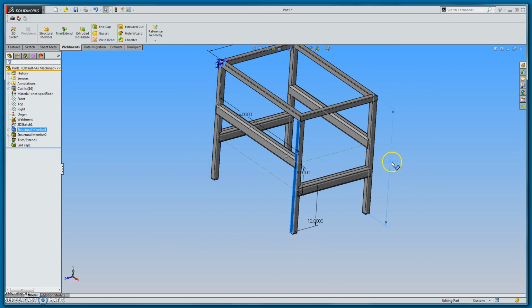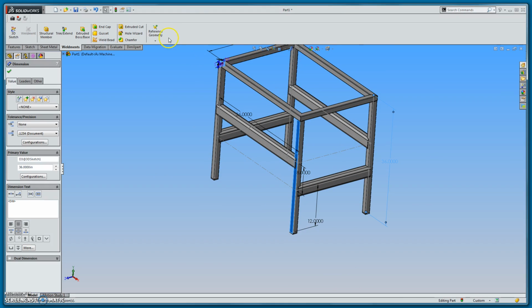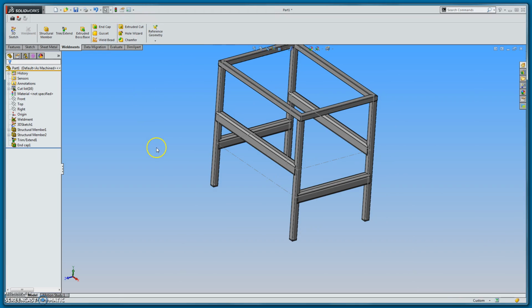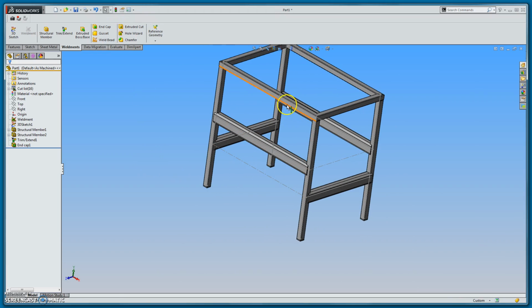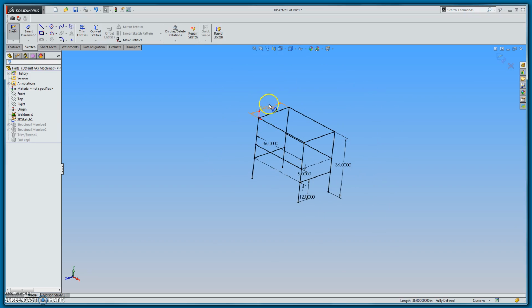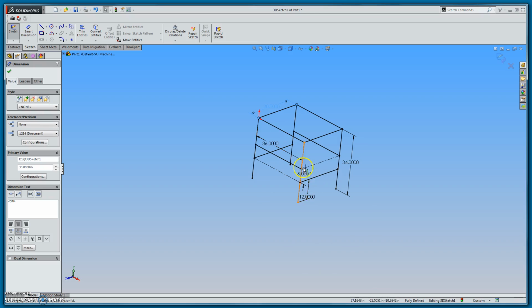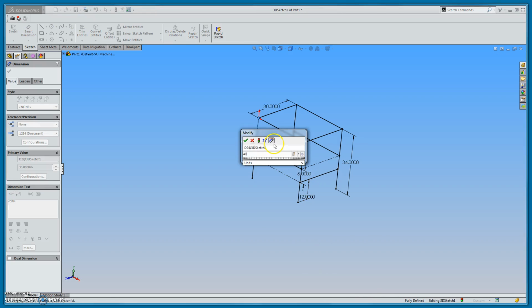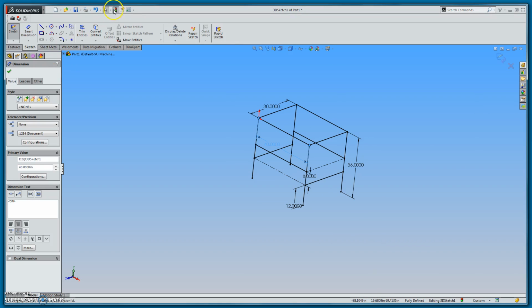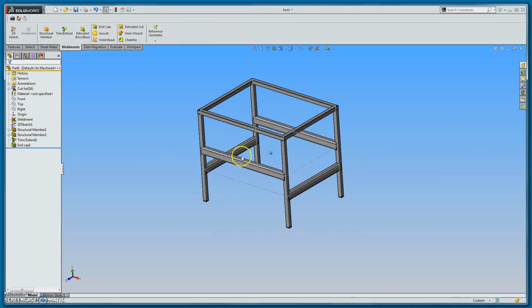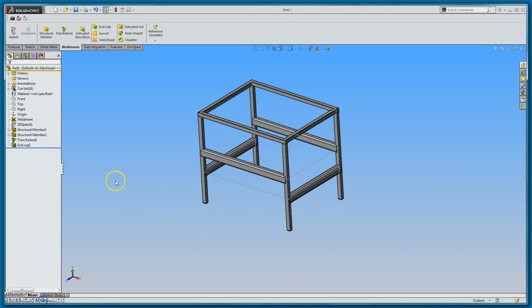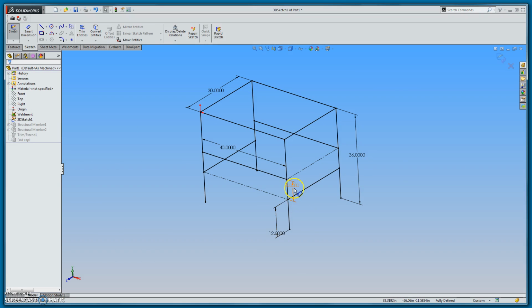In addition to that, I can change my height on the fly. Say I want to make that 36. So all I do is edit my sketch. Table's longer. Make this 30. Make this 40. Rebuild. So that's the beauty of the 3D sketches. All my dimensions are controlled at one control point, this sketch. If I want to raise or lower these heights, I've got a handful of dimensions to get that done.